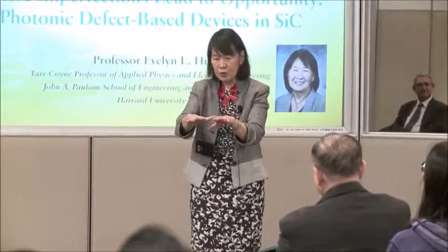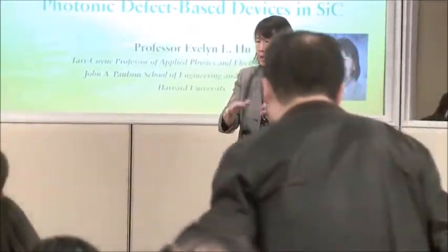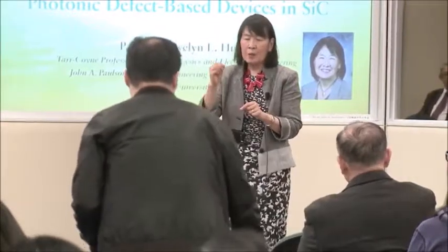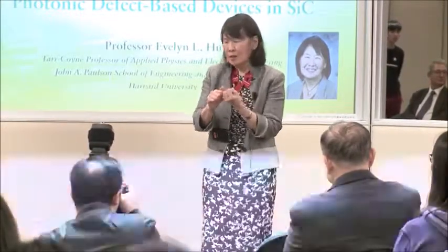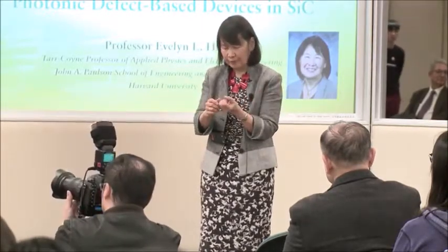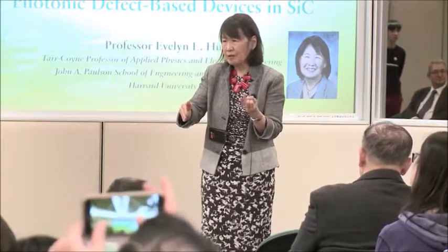People have tried to do patterning and masking, and then bombard either with ions or electrons. People have used specially designed focused ion beams to try and place ions in the right place. There are two issues. One is the residual damage, although we do annealing steps often. Two is that you know that you can do simulations, but ions don't go where you want them. They scatter.